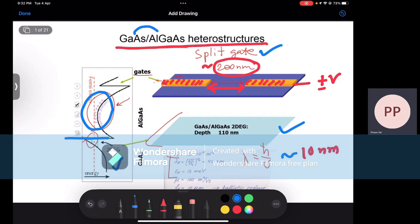And you can think of it as a capacitor. You induce a negative charge on the gate, so you will induce a positive charge on the 2DEG. Since electrons are negative charges, adding positive charges is like removing electrons from the 2DEG, right?